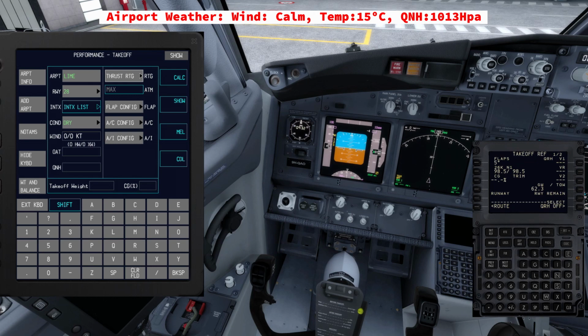And then every aircraft, depending on the conditions, whether it's a dry, a wet, or a contaminated runway, has different crosswind components. There is not only one crosswind component. So let's say, for example, 33 knots crosswind component is good for a dry runway on the Boeing 737. But when you have a medium to poor braking action, or the runway is contaminated with snow, this crosswind component